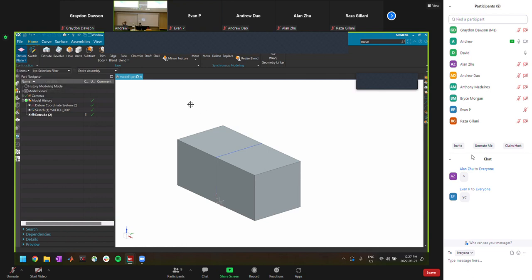In SolidWorks, you can't choose that, but you have dimensions to the part that you have. Here, you can dimension to that new origin, right? Yeah, you can make new origins all over the place, so potentially you have fewer dimensions at the same time. So the thing with NX is using the datums and using that reference geometry to create your datums and working off of those. So does everyone have their rectangle?